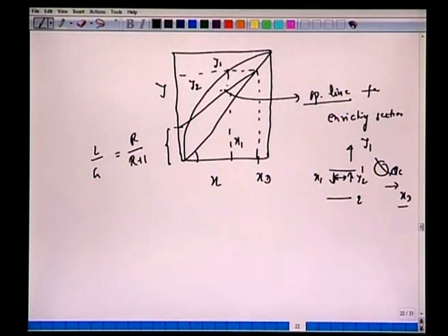So we have a similar story. Tie lines give us equilibrium: the two streams leaving the stage are in equilibrium, and the streams which arrive at and leave stage 1 are connected by the operating line. So again we start with x_D, same as y_1. This line satisfies the operating line. As we said earlier, if you take the slope of the operating line and start from the intercept, we will also reach this point where y equals x.